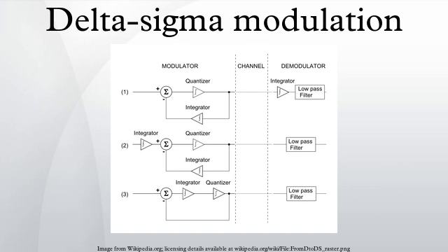The linearity property of integration makes it possible to move the integrator, which reconstructs the analog signal in the demodulator section, in front of the delta modulator. Again, the linearity property of the integration allows the two integrators to be combined and a delta-sigma modulator demodulator block diagram is obtained. However, the quantizer is not homogeneous, and so this explanation is flawed. It's true that delta-sigma is inspired by delta modulation, but the two are distinct in operation.